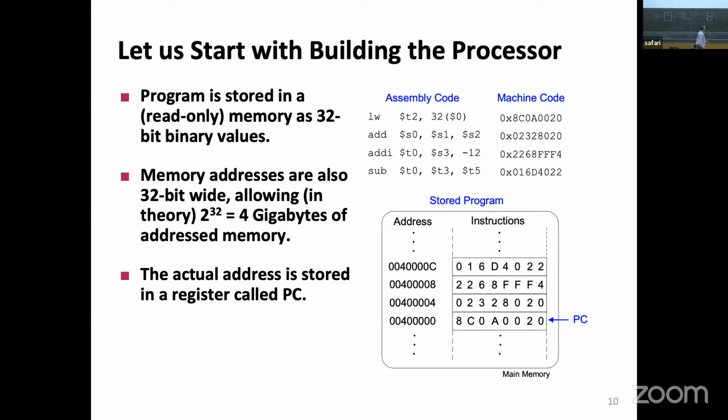What do I do? I take the content of this register and I add a constant to it. Now, the good thing to realize is the first register is easy. I have it here. From the instruction, I read the first register. It comes here. I go to the ALU. And the ALU can do the addition for me, no problem. So we can go here and, sorry, of course I have to try it four times to get it done. We say, hey, let's do an addition, whatever the function code is for addition, we will be good.